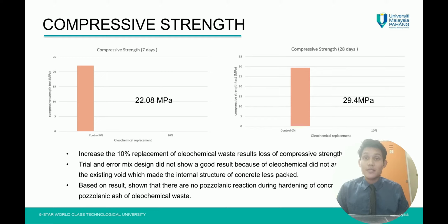The trial and error mix design did not show a good result because the oleochemical waste did not act as a filler to fill up the existing voids, which made the internal structure of the concrete less packed. Based on the result, there is no positive reaction during the hardening of concrete due to the inactive pozzolanic ash of the oleochemical waste.